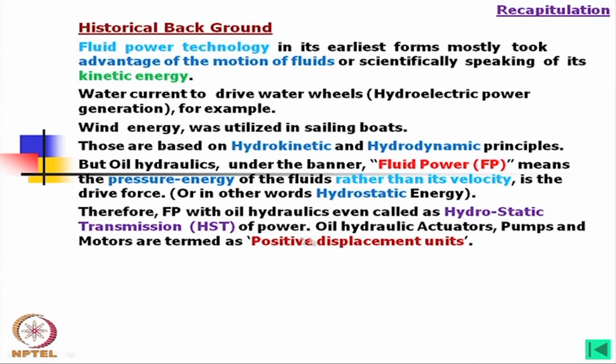And therefore, in positive displacement units, if you calculate the geometric displacement, that means the volume displaced per revolution, we call it swept volume. Okay. So, it has a swept volume. Of course, later in real calculation we have to add how much loss there is, leakage and other losses. Anyway, you should remember this term, the positive displacement unit, and also